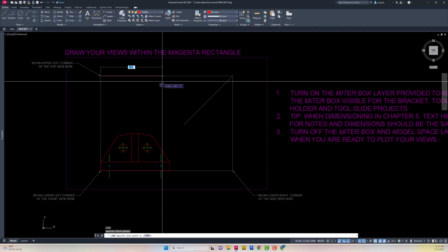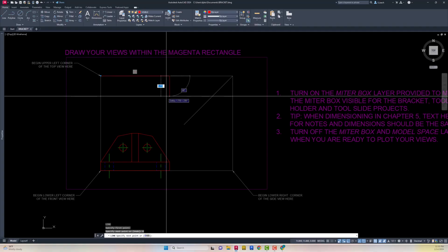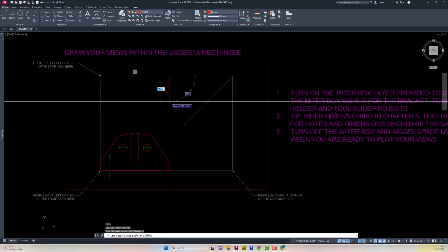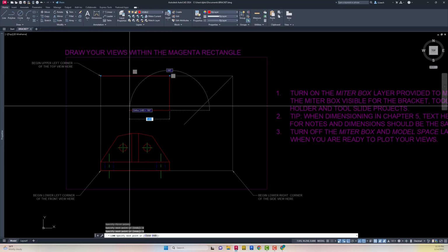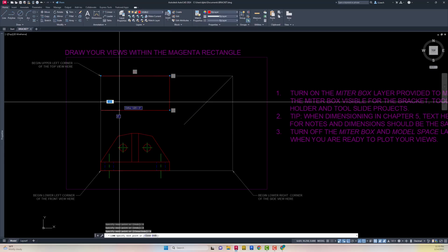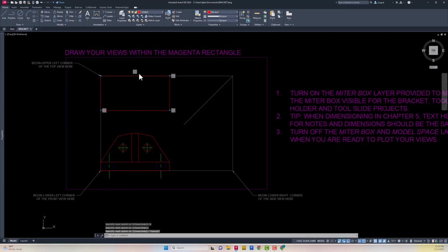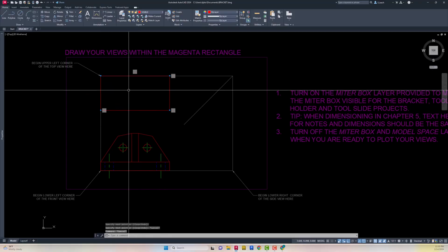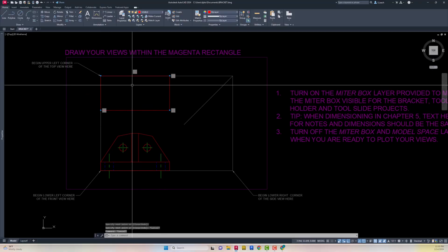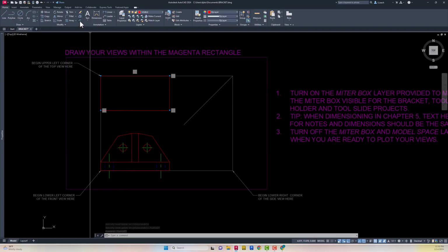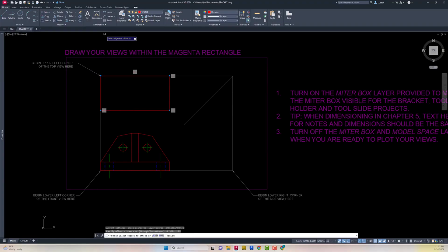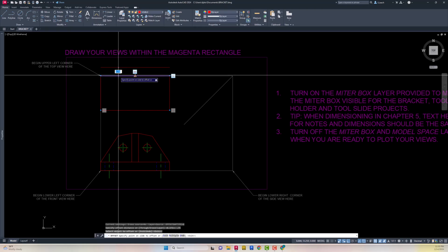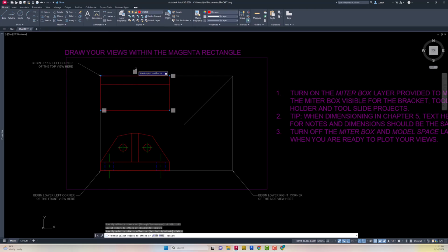I know that's 6 inches, so 6. And I know this thickness goes down. Well, let's just do the whole thing. This is gonna be 3. And then this is gonna go over 6. We're gonna close this over here. I can escape. I'm gonna offset, and that has an offset of 0.75. So I'm gonna offset 0.75, press enter. So this line offset down.